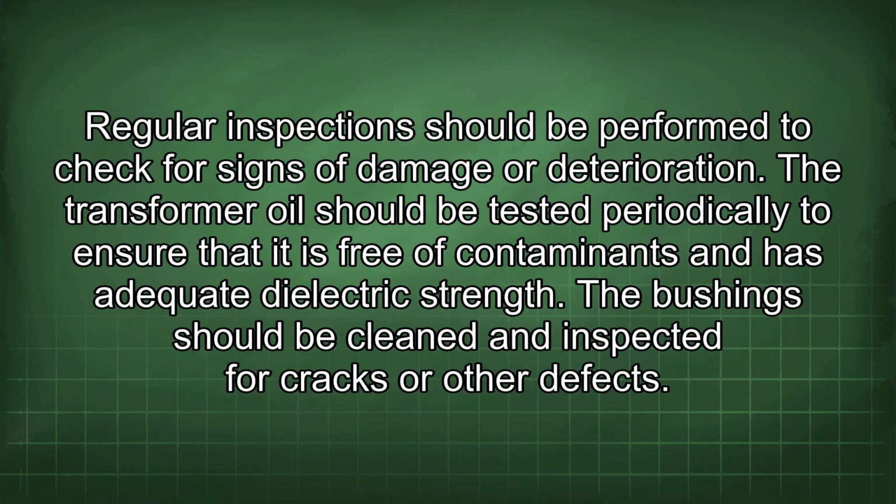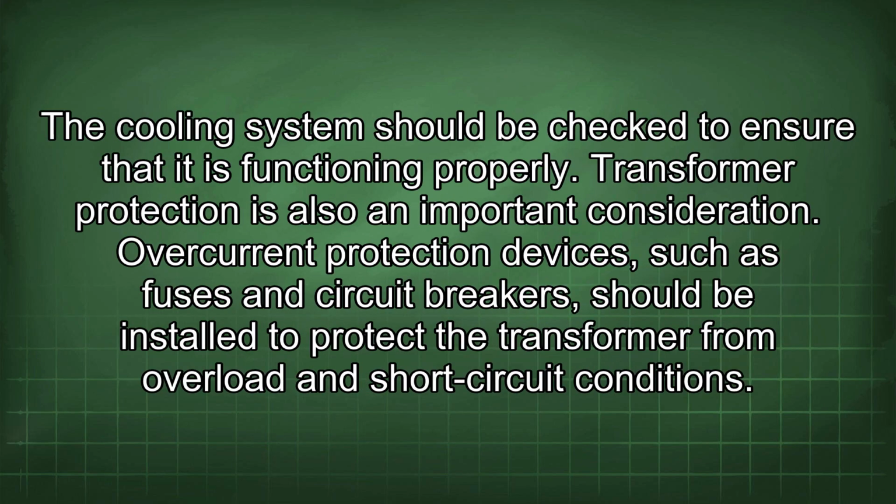Regular inspections should be performed to check for signs of damage or deterioration. The transformer oil should be tested periodically to ensure that it is free of contaminants and has adequate dielectric strength. The bushings should be cleaned and inspected for cracks or other defects. The cooling system should be checked to ensure that it is functioning properly.